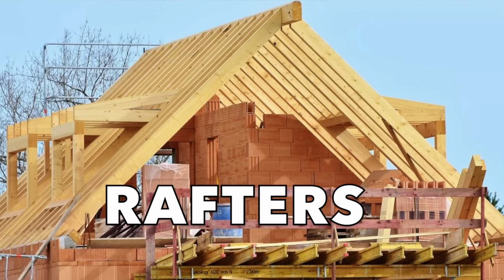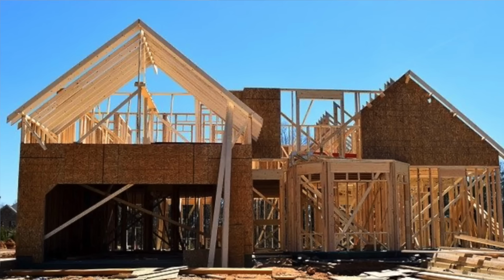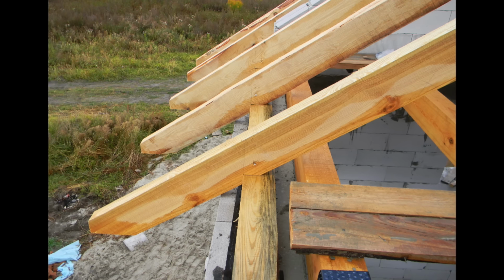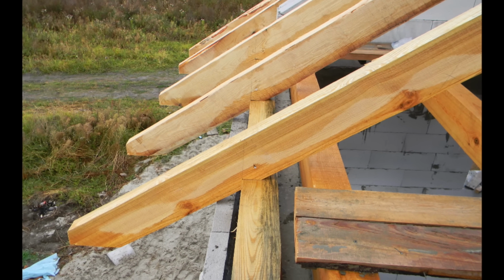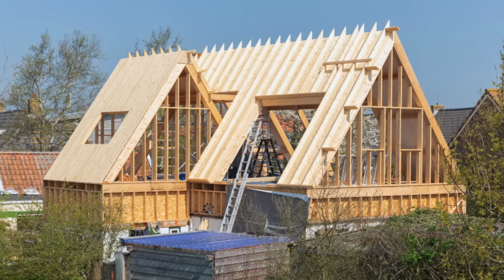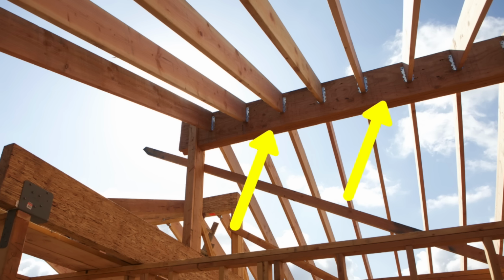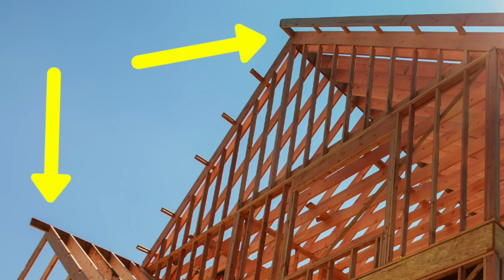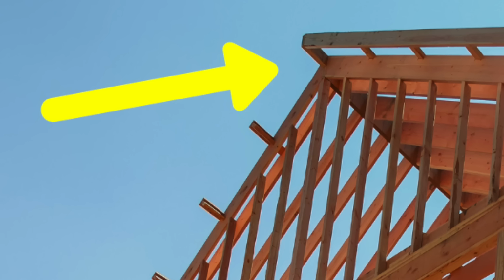Roof framing is a complex topic because things stop moving in 2 dimensions and they start converging in 3 dimensions. In traditional framing, roofs are made up of rafters. Rafters are a lot like floor joists, except they're set diagonally at a fixed pitch. At the bottom, rafters sometimes sit on the top plate of the wall below. Other times, they sit on yet another floor structure in the attic. Rafters typically travel upward and converge at a ridge board. This is a fairly tall board that gets sandwiched between rafter peaks. In houses with gables, the ridge board runs all the way out to the exterior wall and sometimes beyond.